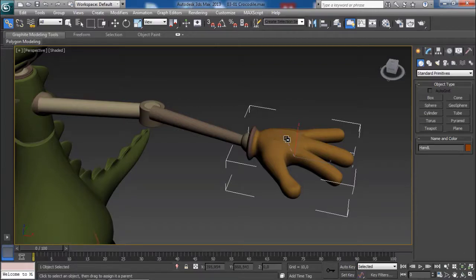Okay, so keep this in mind. And always make sure you are selecting the appropriate object and make use of the icons that show up to know if you're going to pick the right object or not. Okay, so still holding our mouse button, and when our cursor is on top of the right object, all we need to do is release our mouse button, and there we go. We have now managed to set a parent-child relationship between our two objects.